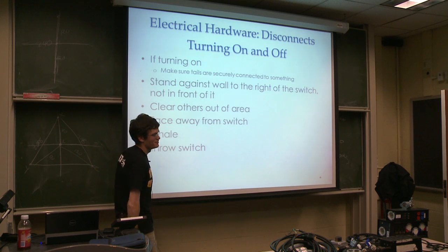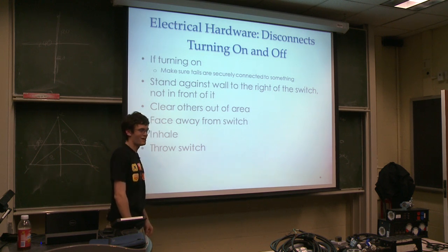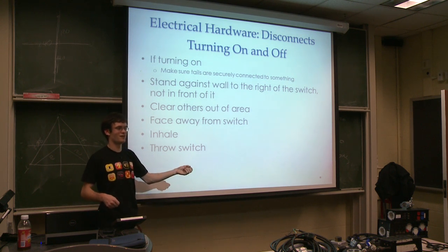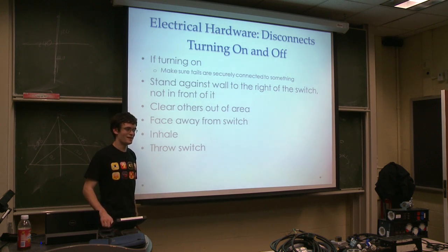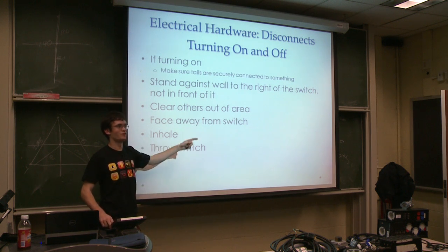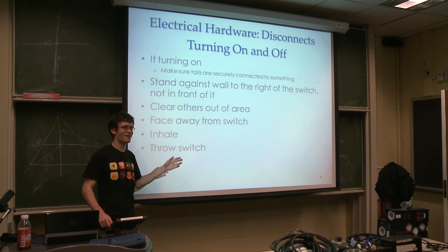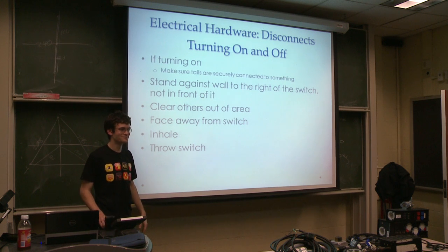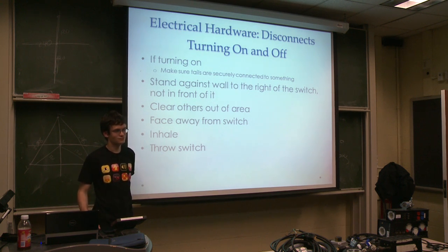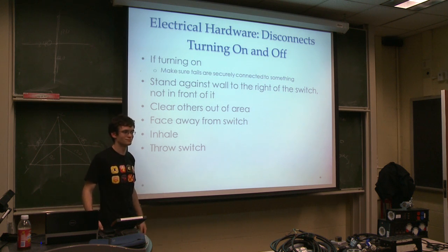Story time. During, I think, DS last year, it was discovered that a neutral feeder line had popped out of the Camlock connector and was just sitting there. And what happened is we ran over to tell front of house that he was losing sound and then turned the disconnect off right away. Well, what you probably should have done is thrown all the breakers on the distro box to remove the load from the disconnect before turning it off.